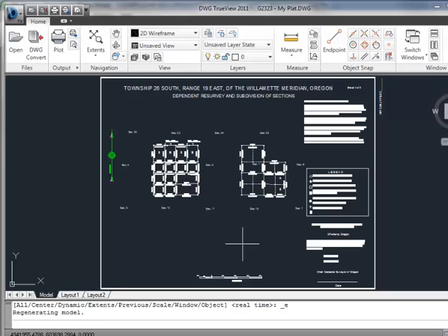And what's nice about the drawing that comes over is that everything's ready to go basically as if I had drawn it in CAD. So the north arrow is a block. The scale bar is a block. The paragraphs are M-text. Polylines are polylines. I have the layers that I used inside of Traverse PC become layers inside of CAD. We don't care what CAD program, whether it's an Autodesk product or a Bentley product. It really doesn't matter to Traverse PC.